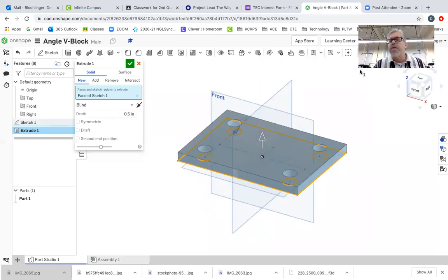Here's the part that I probably should have practiced. I know we need this top part rotated. So the front plane, we need to rotate 45 degrees. And then we're ready to draw. And we're going to extrude it symmetrically both directions. And we're done. All right. So let's see if we can get this plane going.